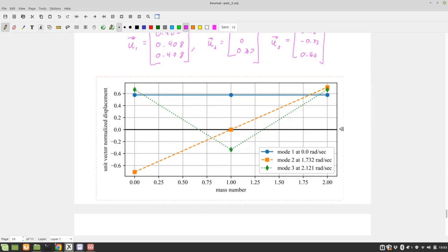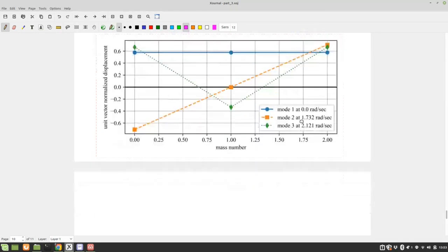You know, you could adjust the stiffnesses. Makes you think, will your second mode have more energy than your third mode? Do you want a second mode like this, or do you want a second mode like this for controllability? How do you want your wing surfaces to deform? I feel like if you have this, you might always end up turning to the left. You just adjust your rudder, but I don't know. Thought process.